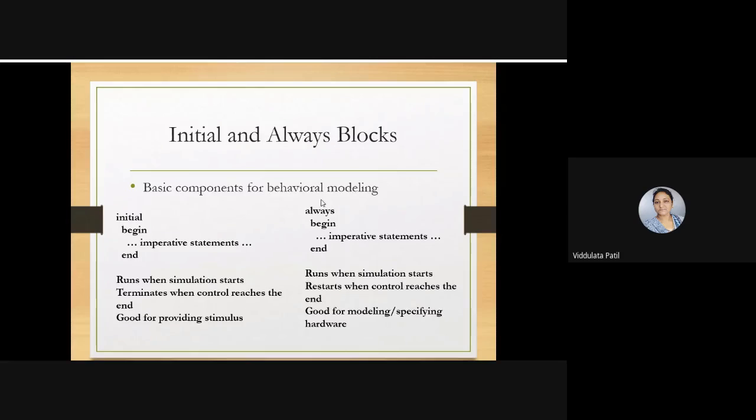And we have another block, that is always. Again, it starts with the keyword always and then begin, there are certain statements present, and then end. This again starts whenever simulation is started.